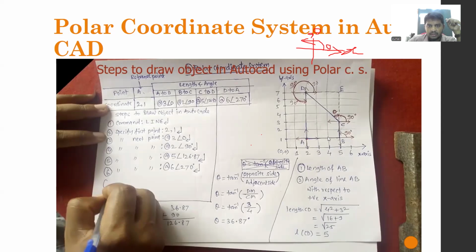From here B 90. The length is 2. 2 less than 90. From here, what is the angle? 90 plus theta. The theta you can measure from anywhere. Here, normally we can measure the theta. Then 90 plus theta, you have to give as an angle, 126.87. What is the length? 5. The 5 you also, by using the Pythagoras theorem, you can measure and you can put. Then from here, D, the angle is starting from here, 270. So what is the length? 6 is the length. So we have to write at 6, 270. In this way, you have to complete this one.